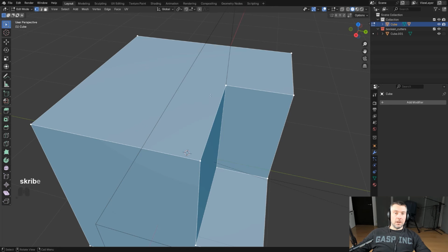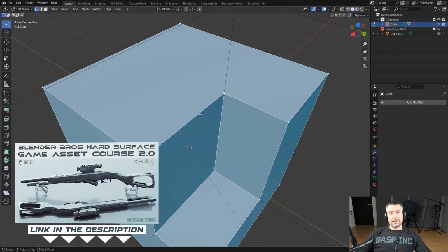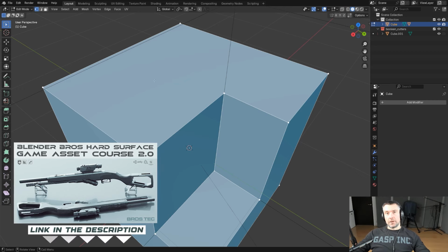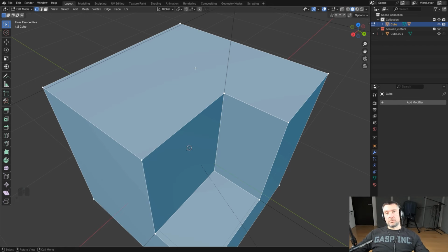If your model doesn't have to be converted into quad mesh, then don't bother with it because it's a waste of time. We have an entire game asset course based on n-gon mesh, and it's fine. Anyone in the industry that actually knows what they're doing will tell you that you don't really need quads in every single model. Okay, there are specific instances when you do need quads, for example, for a mesh that's gonna deform, for certain VFX and video production assets. Not all of them, mind you, some stuff in the background doesn't even need to be in quads.